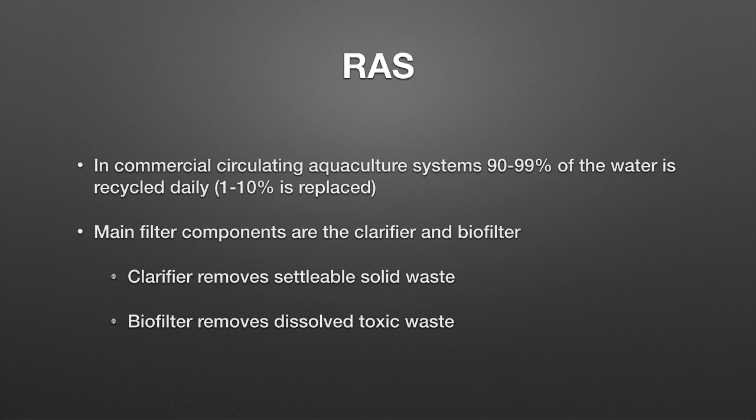In commercial recirculating systems, typically 90 to 99% of the water is recycled or reused daily. So 1 to 10% is replaced daily. The main filter components are the clarifier and the biofilter. The clarifier removes settleable solid waste, and the biofilter removes dissolved toxic waste.